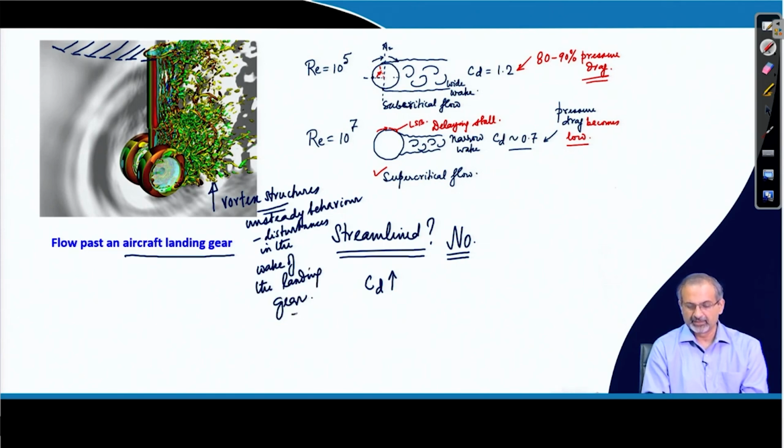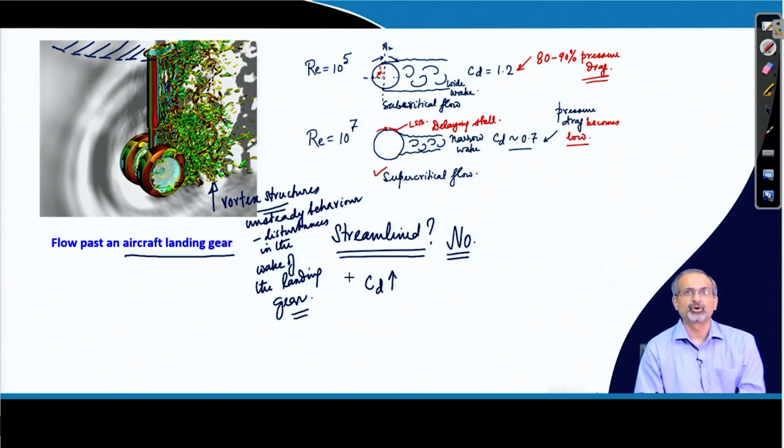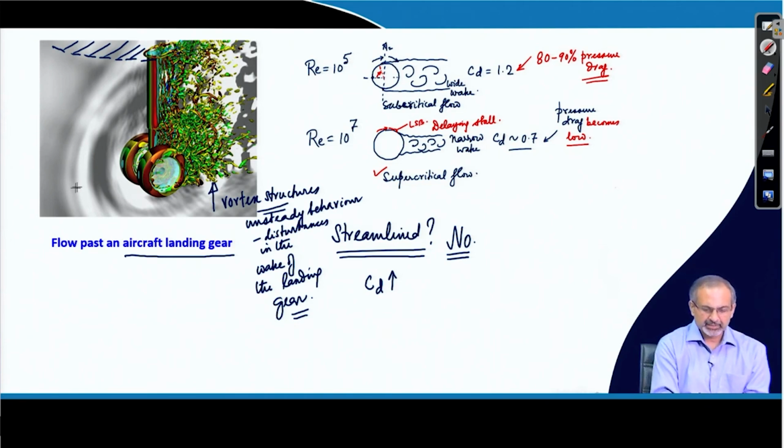Once again, you cannot do it with inviscid models or potential flow models. So, it is again Navier-Stokes that you are solving over here. Additionally, you are seeing wave like structures over here. So, these could be pressure waves, maybe sound waves, these may be generating noise.